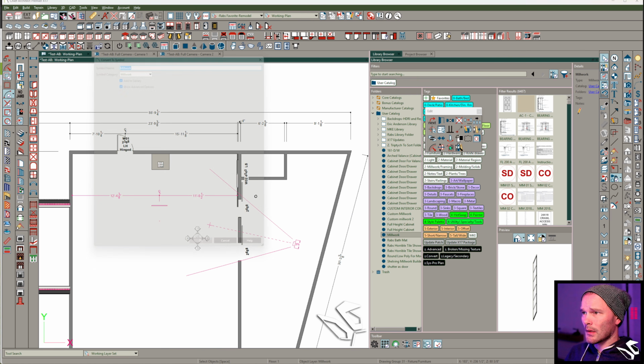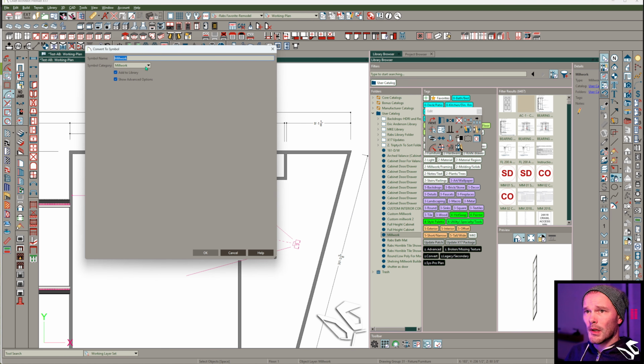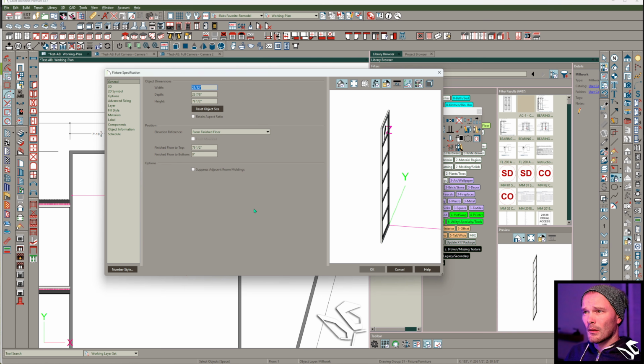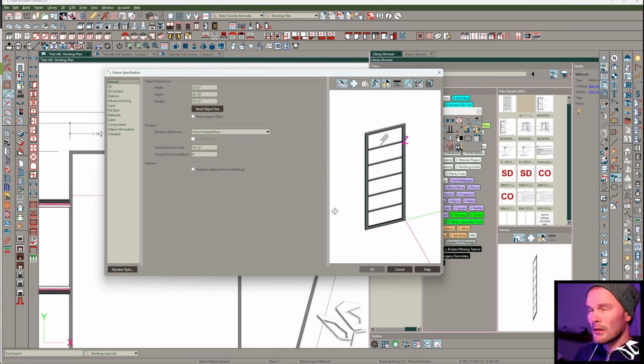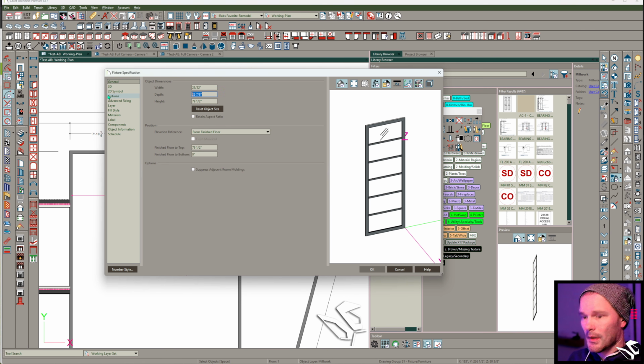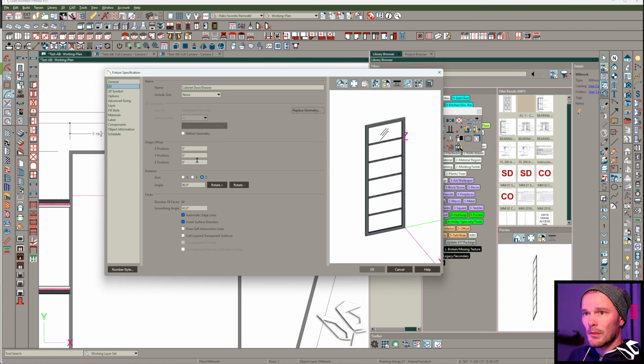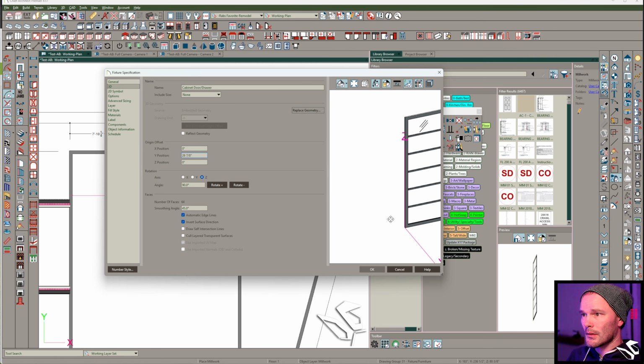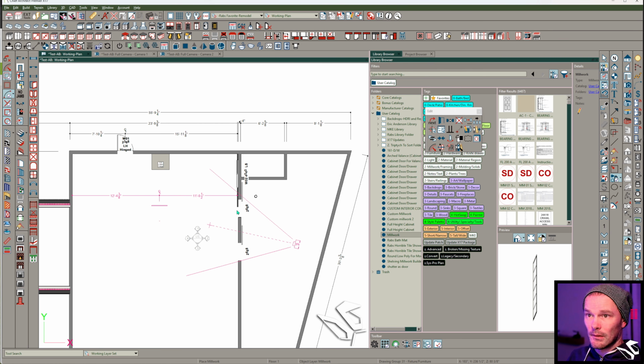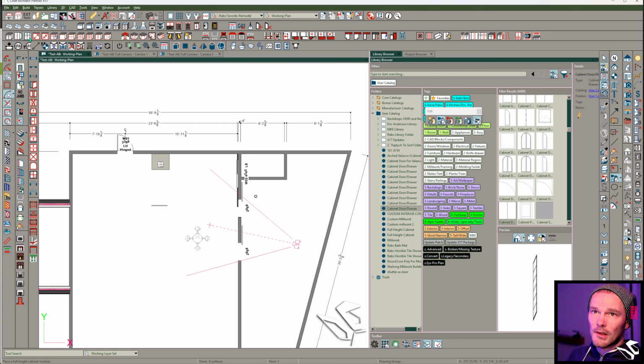Let's take this, convert it to drawer, cabinet door drawer. That is the correct direction, but we need the offset. So the depth needs to get put into the 3D panel's positive Y direction so that that's the front face there. I believe. And let's start with a brand new cabinet.